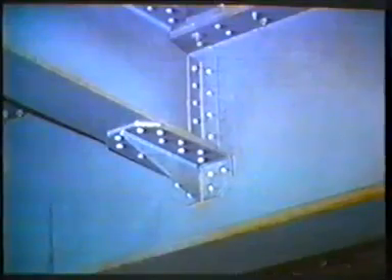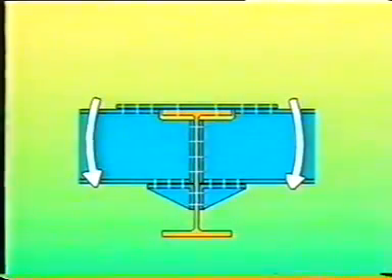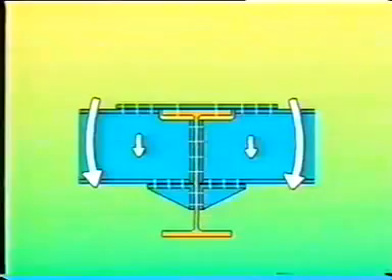Stringers can be placed on top of the cross girder, or the upper flange of stringer and cross girder may be kept at one level using the continuous beam connection. In both cases, the stringer can transmit bending moments and shear forces.